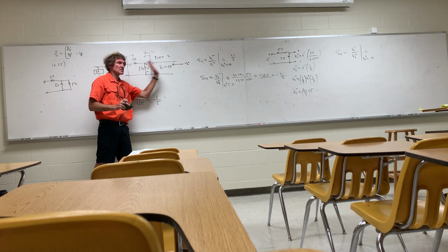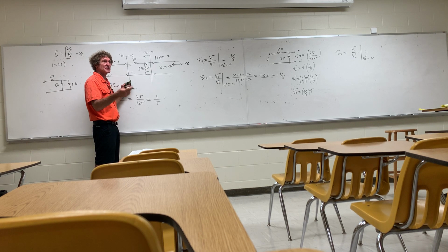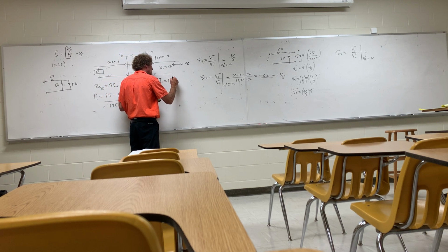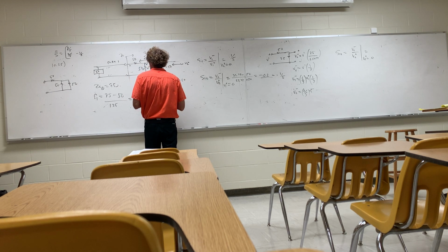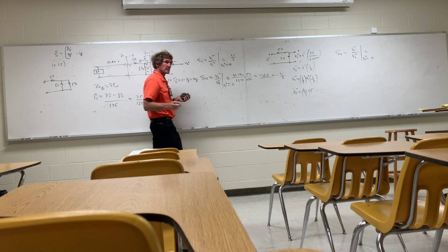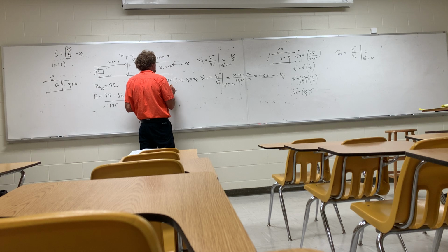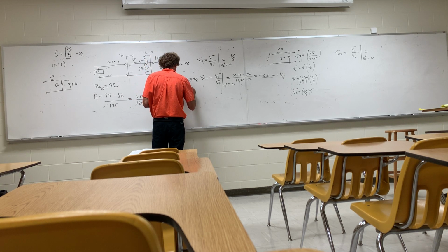So the wave comes in, hits the port, some is reflected and some is transmitted. That's the V prime. So what do I need to get that, guys? Just give it a shot. I need the transmission coefficient, don't I? What is the transmission coefficient at port 2? It's 1 plus the reflection coefficient at port 2. Do y'all agree? So it's really 1 minus 1/5, or 4/5. That means this voltage, V2 prime right there, is equal to the transmission coefficient of port 2 times V2 plus, or 4/5 V2 plus.